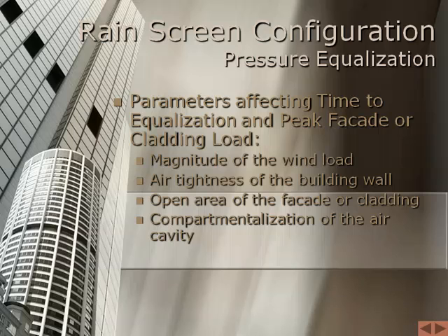The volume of the air cavity. Minimum cavity volume is governed by minimum cavity width. A minimum cavity width is required, sufficient to provide a capillary break, permit drainage of any water that enters a cavity, and allow unobstructed air movement, including convective air movement, to enhance drying. A cavity width of about 1 inch is suitable.